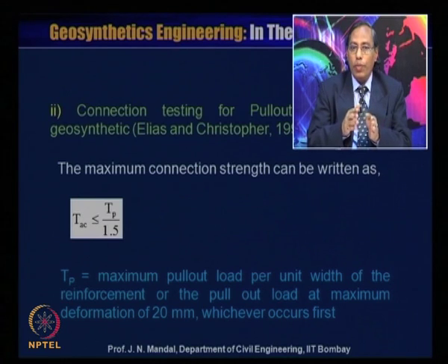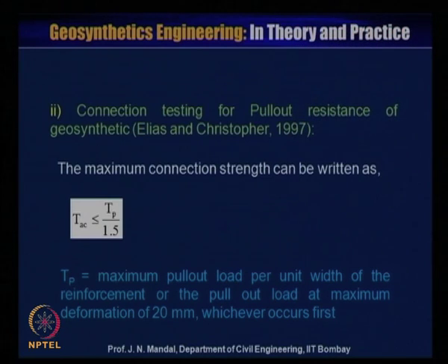So, this is also important, that what maximum deformation you can take. You can take the deformation up to 20 millimeter, or you can say that what will be the maximum pull out of reinforcement from the unit width of the reinforcement. So, whichever will occur first. Accordingly you can calculate what will be the maximum pull out force T_P.